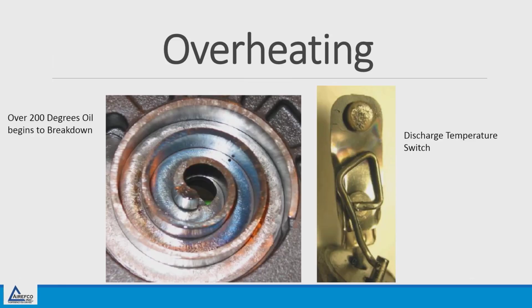Another result of lack of lubrication is overheating. Anytime the refrigerant oil gets over 200 degrees, the oil begins to break down. So it is very important that your compressor has a discharge temperature switch, which will cut the compressor off anytime that the temperature exceeds its limit.